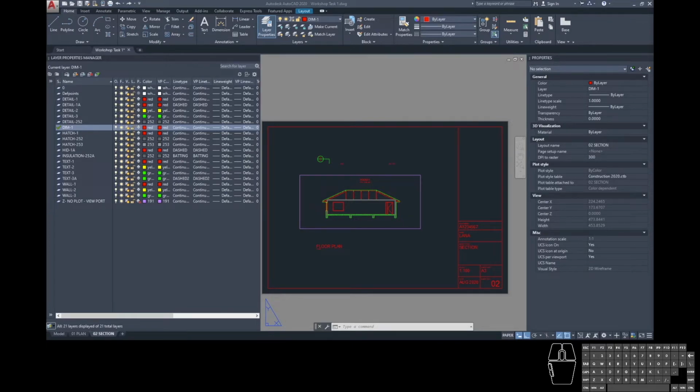What this does is gives us consistency between the sheets and saves us a little bit of time in redrawing stuff like the detail call out, because that's a little bit more difficult, and making sure that they're all the same across each page is one of those consistency things in AutoCAD that's very important. If you have one detail that's repeated across many pages, you want to make sure it's appearing the same on